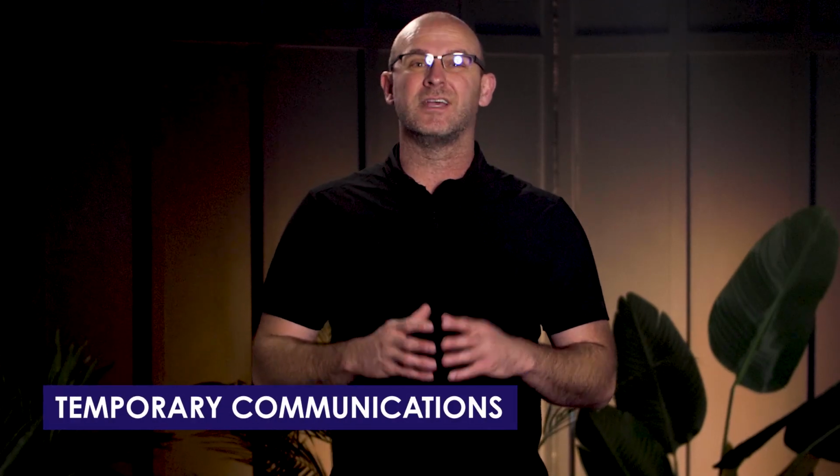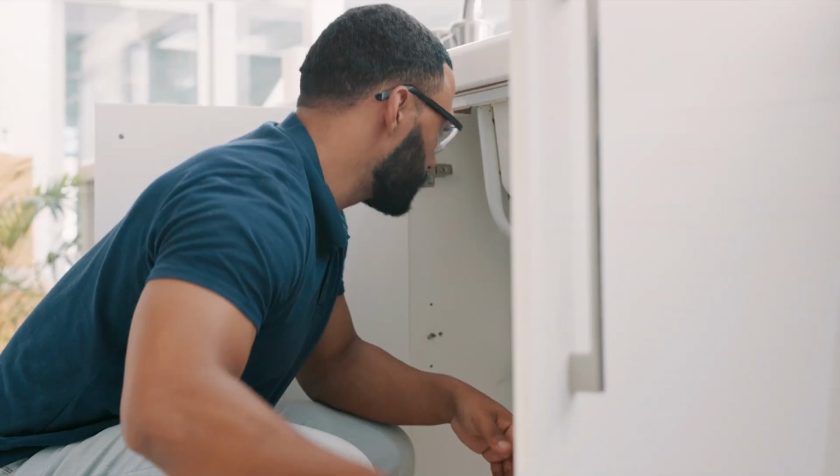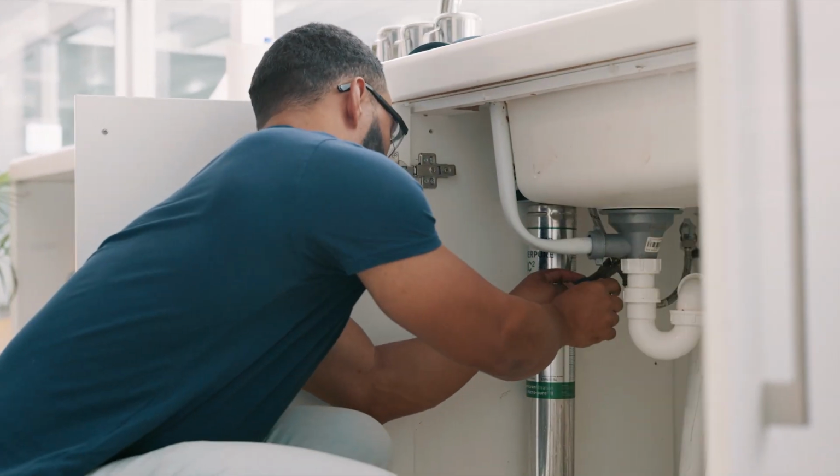Now, water isn't as hard to get as temporary power or even sometimes temp communications. Typically, it's as simple as finding a hydrant, finding a water source, finding a place where you can tap the water main, and then bringing it up in a riser, setting up your backflow preventer, having the city install the meter, getting the permit, and then monitoring your usage and paying the bill. Typically, that's what it's all about.